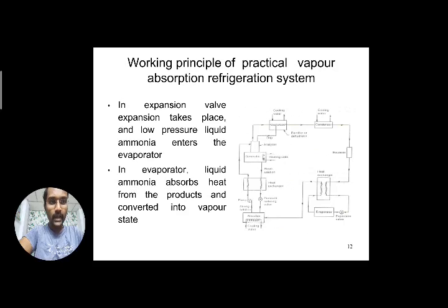So what is the benefit here? At the right side, you see, during entry into the expansion valve, what is happening here? Due to creation of low pressures, low temperatures are created. What we are doing in this circuit after the receiver, we are creating the low pressures and low temperatures when it is passing through the heat exchanger by rejecting its heat to the other circuit of the heat exchanger. Heat exchange is taking place. At one side its temperature is reduced, and on the other side of the circuit, the temperature of the vapor is increased.